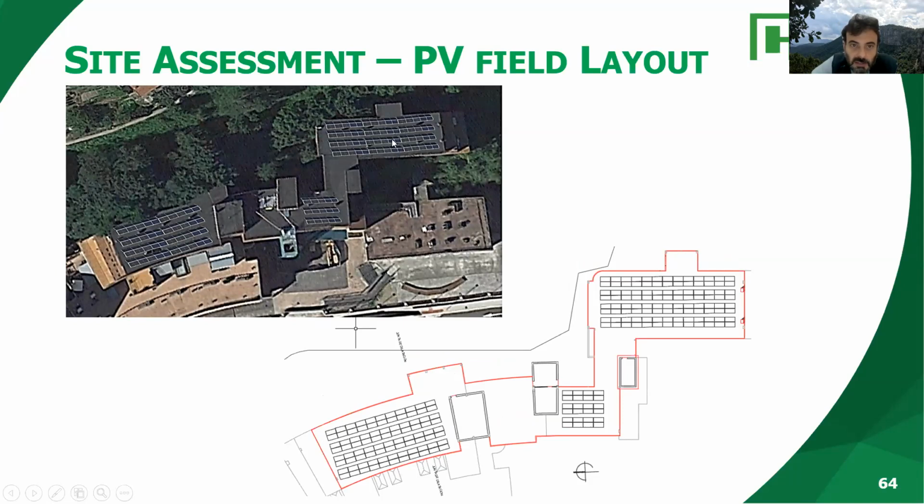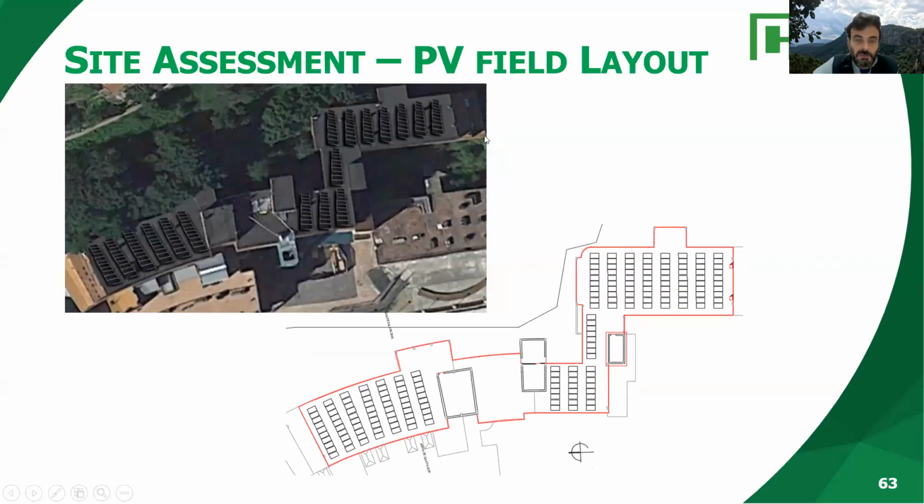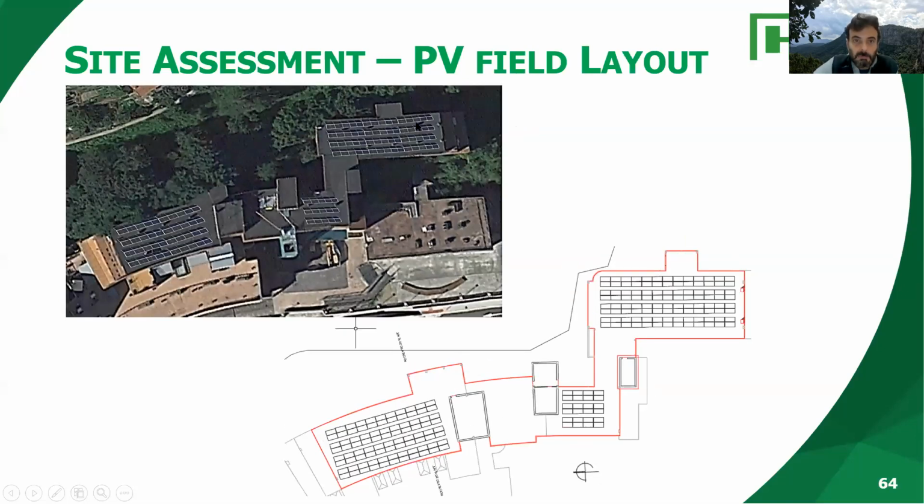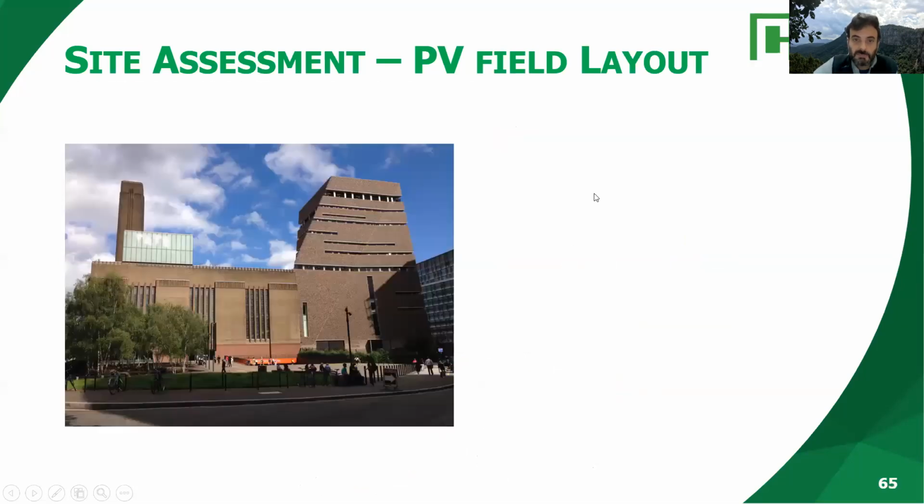This way, we can integrate between 20 to 30% more panels in the same surface, okay? Because there's less shading between each other. We could lose a little bit of productivity, because the panels here are facing north, so very well oriented. And in here, the panels will be facing east and west, so it's not that efficient, but we can put more PV panels to offset, okay?